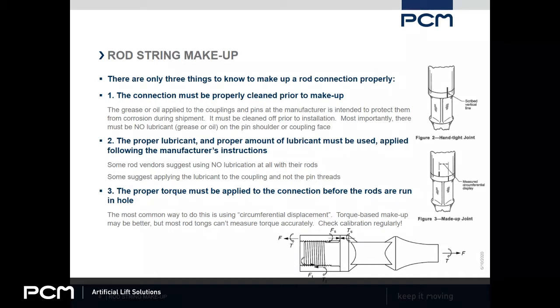Even better would be to use something like brake cleaner that you can buy from an auto parts store. They sell the same product in other stores as electrical contact cleaner. It's really good. I mean, it's a solvent, but it's a very volatile solvent that, after you clean off the oil, evaporates and leaves no trace behind, so you get a very clean surface.